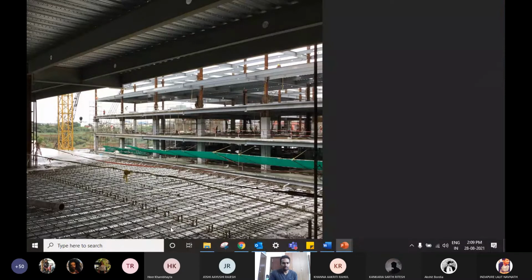Okay, you can see now these are the shear studs. Right, instead of one stud we have two studs, so that means below there is a beam. Now you can make sense of it because by looking at the beam above, this is a typical floor which is replicated onto the other floors. So you can see a steel beam, and they have some web penetrations for the conduits to run through for mechanical and electrical purposes.